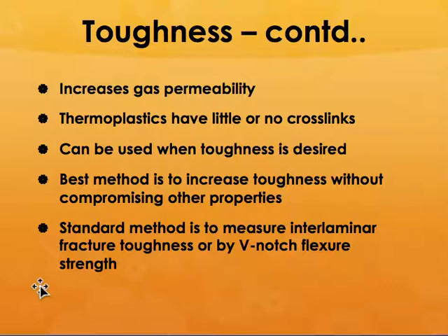So you have to worry about all these things in order to get good mechanical properties and other properties like delamination properties. The other issue that might happen is that if you add these kinds of particles, they may not exactly improve the bonding between the matrix and the fibers, which means that it increases the permeability of gases through this system.